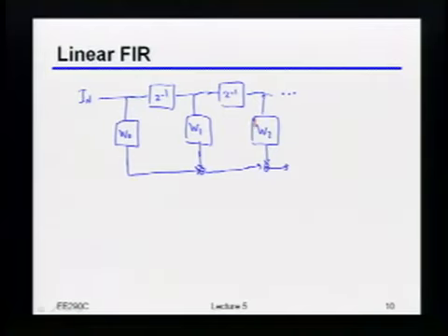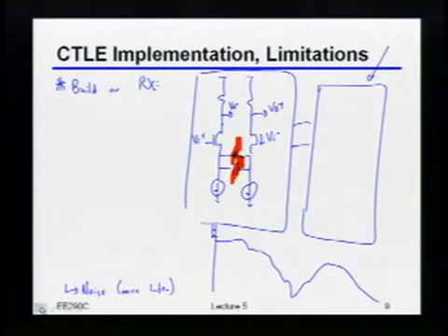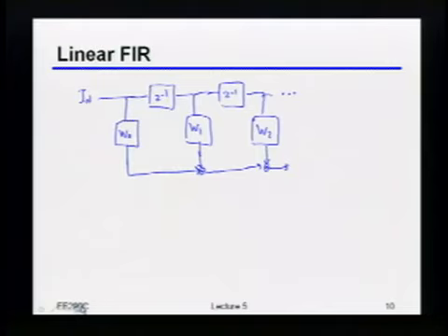I'll talk a little bit more in a second about where or how you'd implement this, but let's assume that you can implement this one way or another. What's potentially advantageous about doing the equalizer this way versus trying to build it out of a circuit that looks something like this? Any thoughts? You have more flexibility and you can easily make it adaptive. Yeah, that's basically it. It's more flexible in the sense that each one of those taps has an independent coefficient, right?